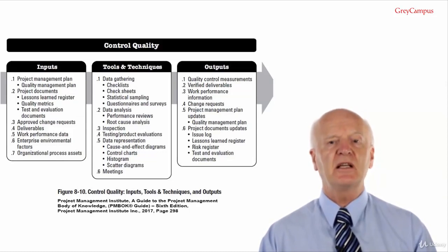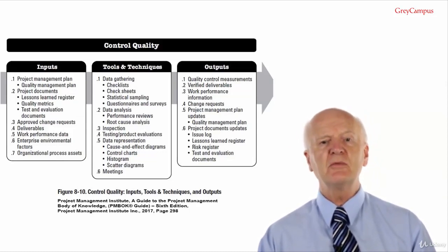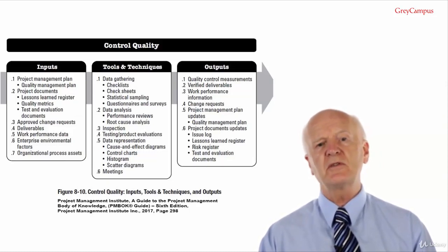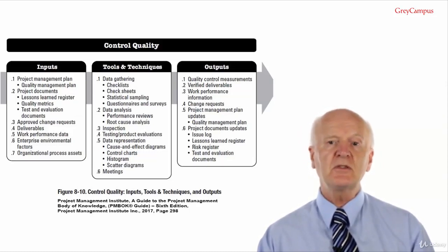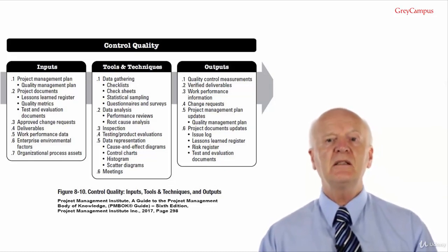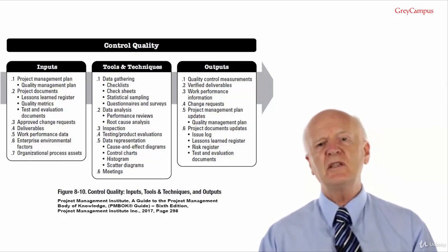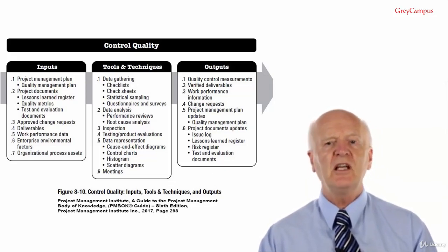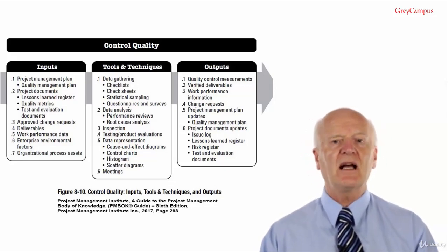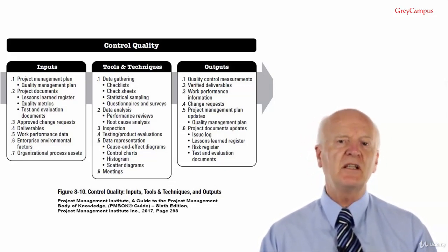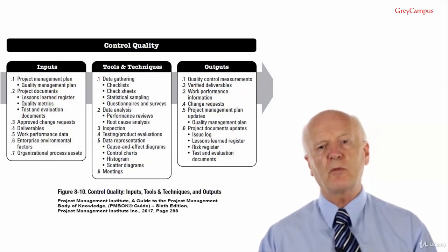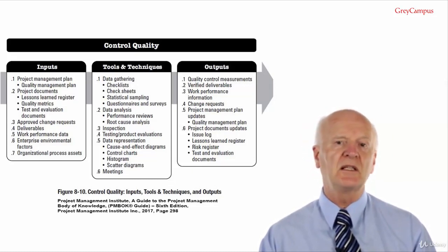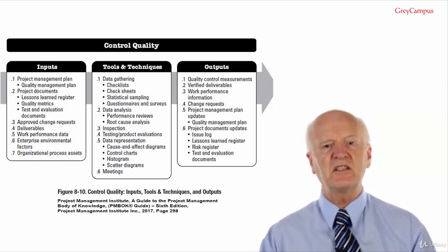Statistical sampling. With large numbers of products, it is usually impossible to test them all. And in fact, if you were trying to test them all, then either your quality assurance system has serious issues or you do. You need to test a sample instead, but if you test the first 10 of each 1,000, you may be actually testing items from an individual batch or an individual machine, and so that's not representative of the whole products. You have a similar problem if you test items at fixed intervals, such as each 10th.